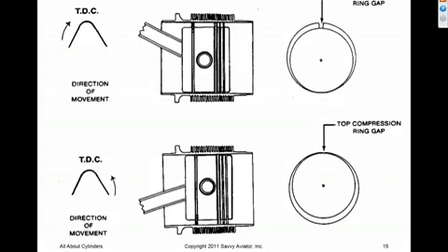The compression test has a lot of false positives, so nowadays the trend is to not pay nearly as much attention to compression readings as was the case 10 years ago. In fact, if you plot out the compressions on a particular engine year to year, you'll typically see that a particular cylinder will have a compression reading that goes up one year and down another year and then back up the third year and so on. And when the compression gets better, that doesn't mean the cylinder is unwearing or getting into better condition. It just means that there's a lot of noise on the data.